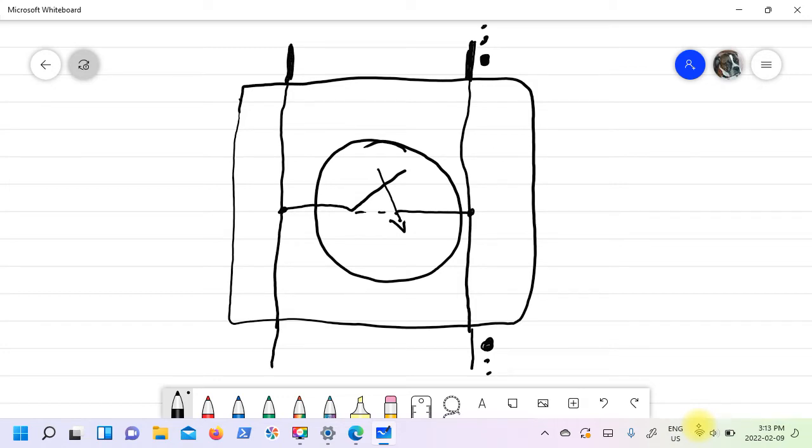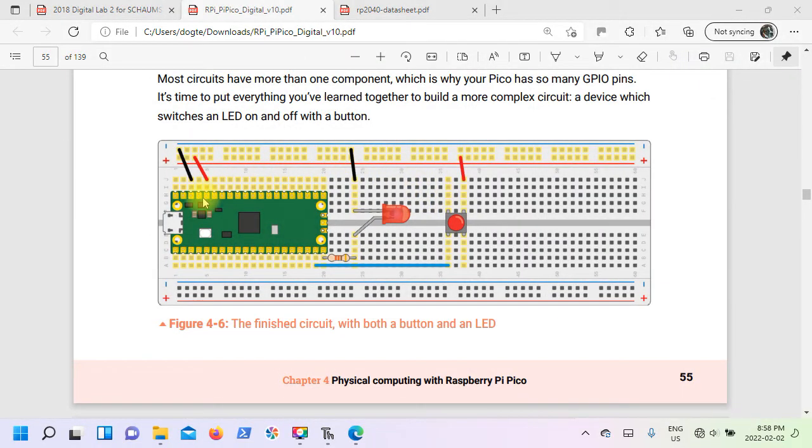to this pin here. So if we're looking at this circuit from your Pico, they're going from the 3.3 volts to the power bus, from the power bus down to the switch. So this line here is connected through the switch all the time to this set of 5 holes. Now when you press the button, the 3.3 volts connects to this set of holes, which are connected to this pin on the other side all the time.